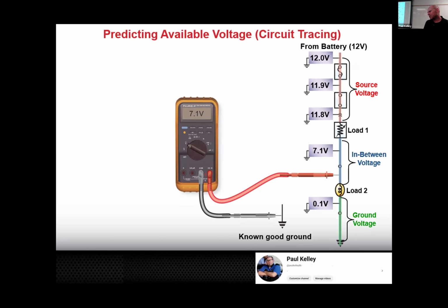And then the other thing is, they do make lead extensions that roll up in a little spool. And sometimes if I'm struggling to find a chassis ground, I'll just bust out the extensions and stretch them out. I'll go right to the battery, and then I've got my ground anywhere and I don't have to take clips out and find it. So some different options. We will do that on the car. Okay, I'm going to give you just a mini lesson in predicting.